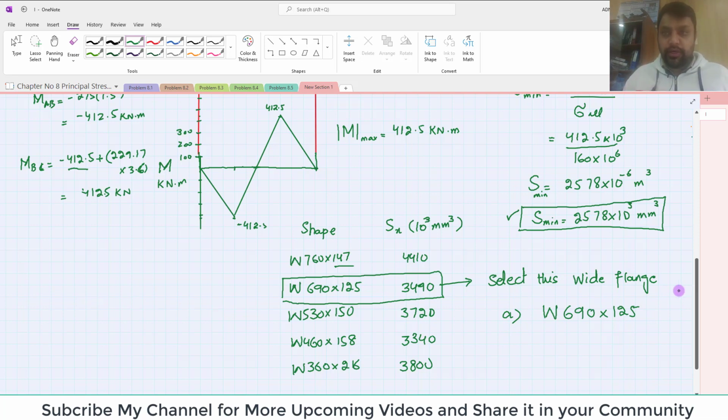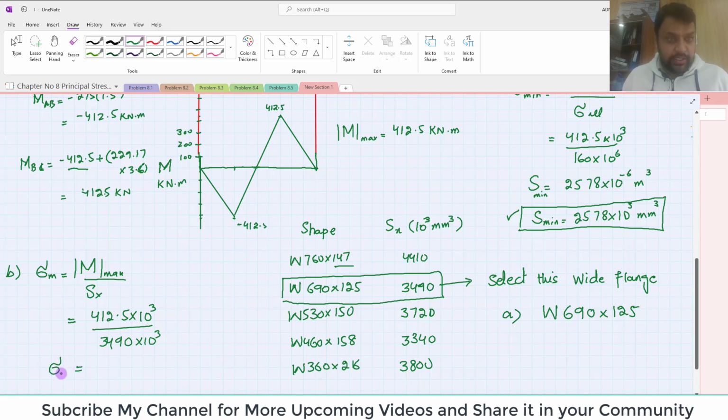So this is the answer of part A. Now we will move toward part B, in which you have to find sigma m. Sigma m means sigma maximum, which is the maximum bending moment divided by section modulus. The maximum bending moment was 412.5 into 10 to the power 3 kilonewton meter, and the section modulus is 3490 into 10 to the power 3. When you calculate it, you will get maximum bending stress, which is 118.19 megapascal.